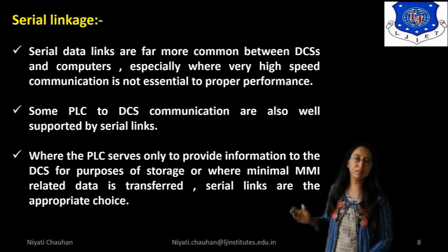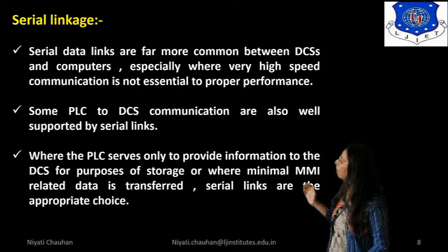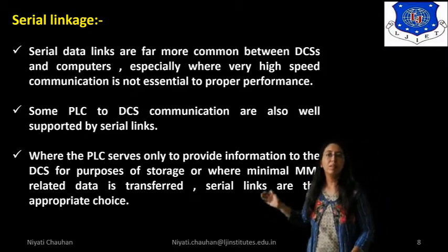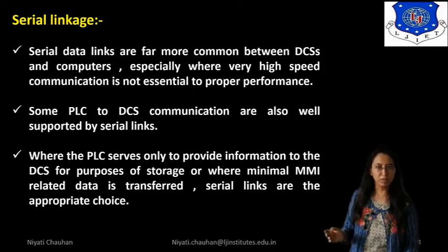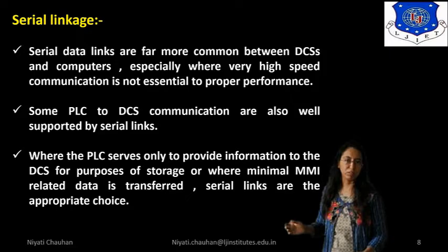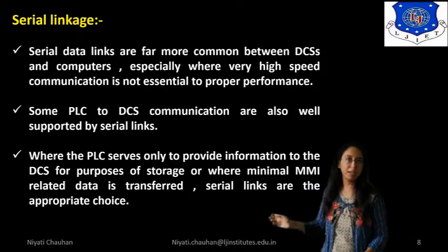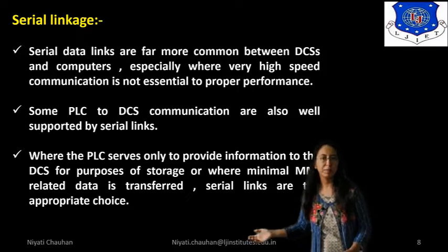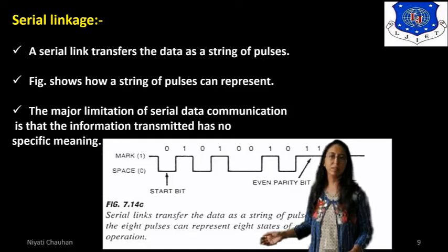Some PLC to DCS communication is also well supported by serial link, where the PLCs are only to provide information to the DCS for the purpose of storage, or where minimal HMI related data is transferred. Serial links are the appropriate choice.